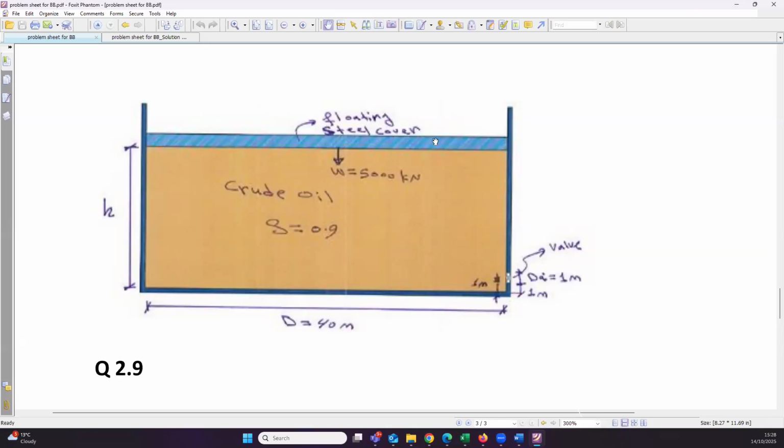In this question, you are to calculate the pressure at the center of this valve. You use the simple rho gh equation, and you calculated the pressure here. So at the center of this valve, the pressure was rho gh plus the pressure due to the weight of this lid.